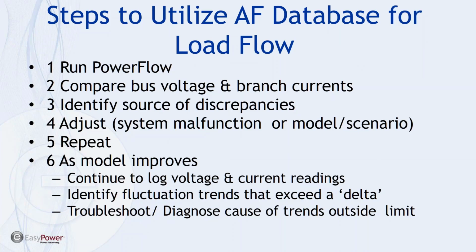So bottom line is we run PowerFlow, we compare the bus voltages and branch voltages, which we take multiple times, and this can be installed monitoring, portable or manual data collection, or it can be data loggers that we put around the plant.